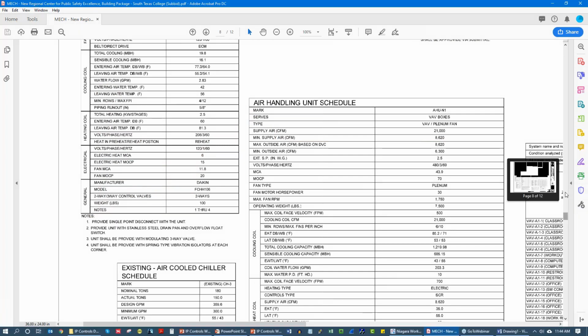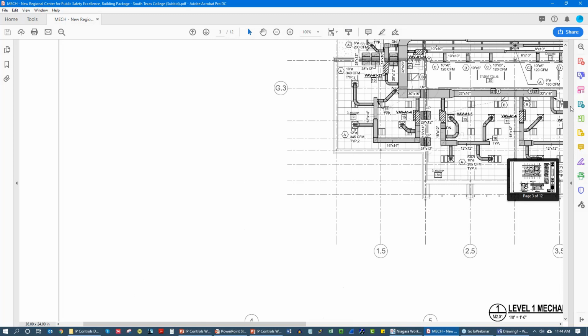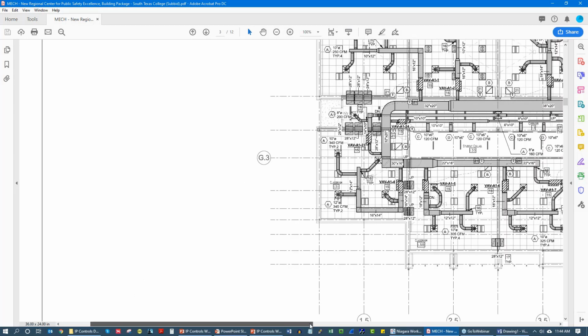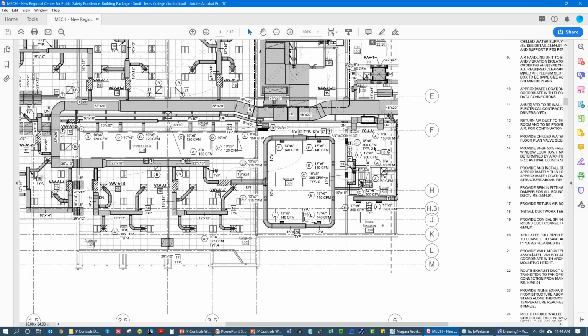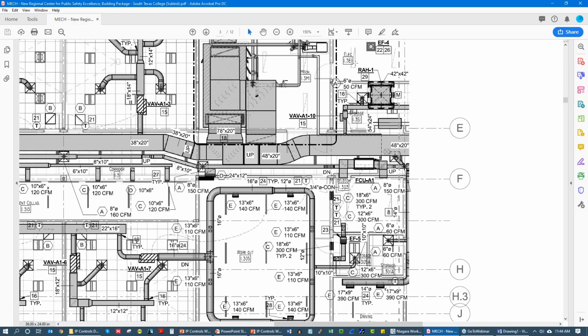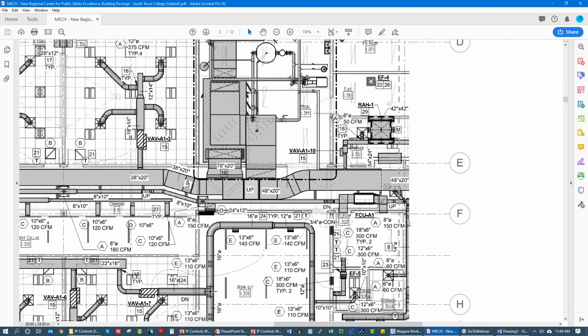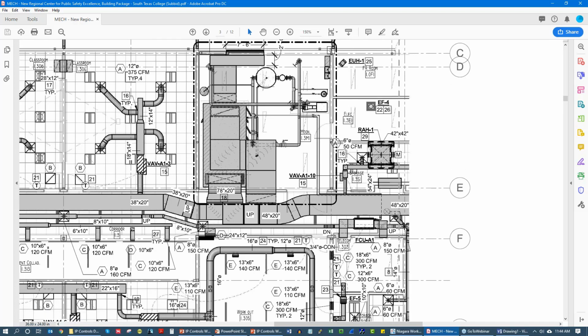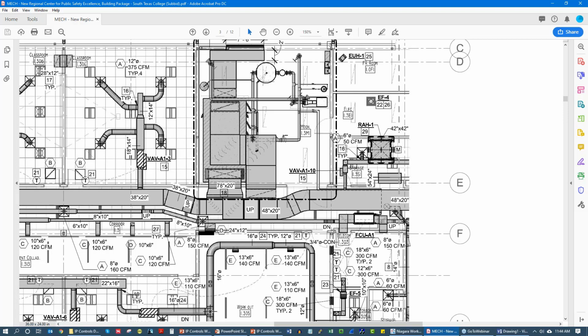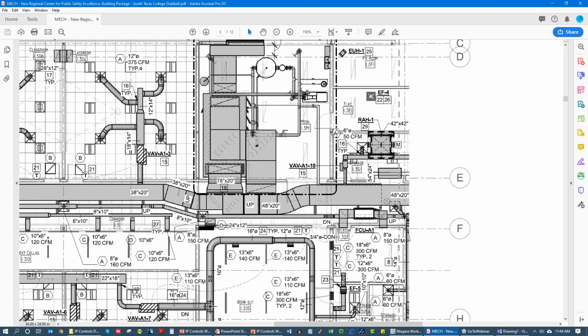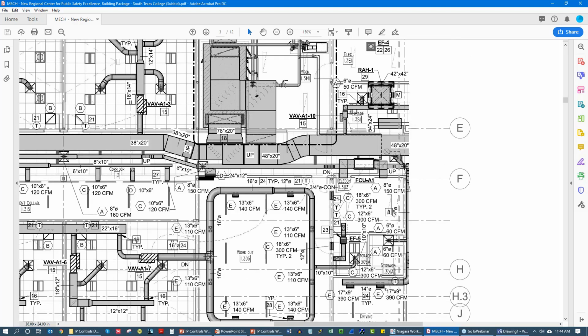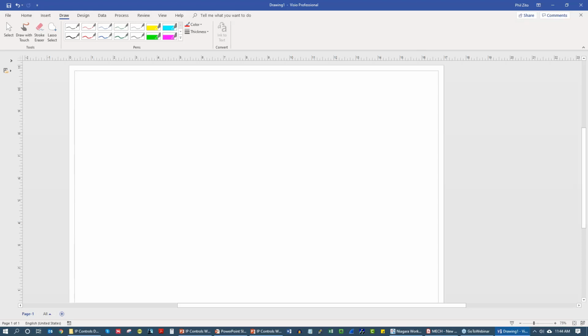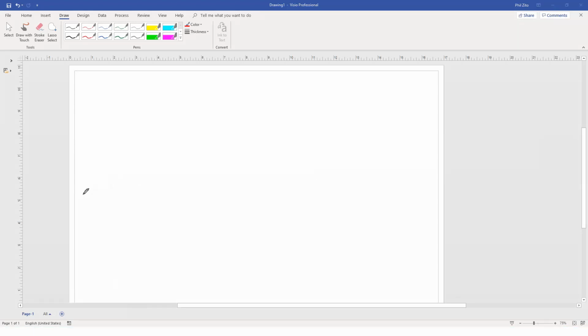Here we go. And if we go back to our drawing, we can see that we are going to find most likely an IDF or MDF somewhere around here. So we've got an electrical closet. We have a tech closet somewhere in here, I know, because I've looked at this set of drawings before. Telecom right here. So our switch is going to sit in here, and then we would just start from our switch and move controller to controller to controller. All right, pretty straightforward. Now I know I cleared all that off, but give me 1 second and I'll get to your question.